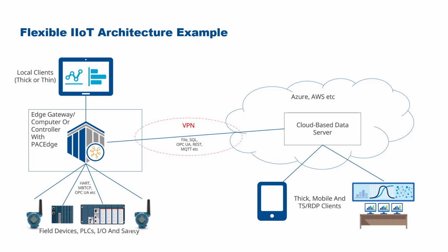So that local client could be a FIC client. It could be connected directly. You've also got the option of using DisplayPort and USB, of course, or it could be a thin client, using web technologies or other technologies. And then you've got the computer itself, the edge computer, that supports integration with all of the field devices, IO modules and safety modules and so on. And we support a variety of protocols there. So as we've seen, Modbus TCP, OPC UA, etc. And you can just stick with that.